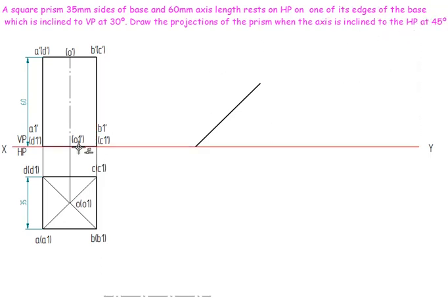Now this base edge is going to be perpendicular to the lateral edge. So if I'm going to click this is going to be 90 degrees. I need to make this base 90 degrees. So from this point, I'll be drawing another 45 degrees angle, and the length of this line is from here to here, which is equals to 35.